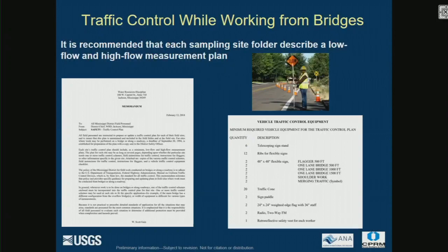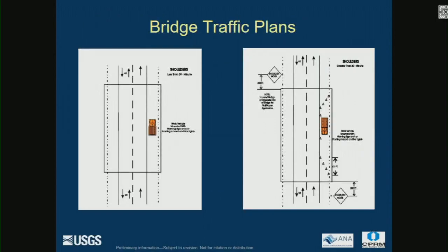The way we developed this years ago was we worked with our local state highway department. They have these plans already in place that work for them when they have to do repairs on the road, when they're doing road construction. And so we follow their lead in the plan that needs to be out, the number of cones, and it specifically is designed to show how many feet this sign's shoulder work ahead needs to be.